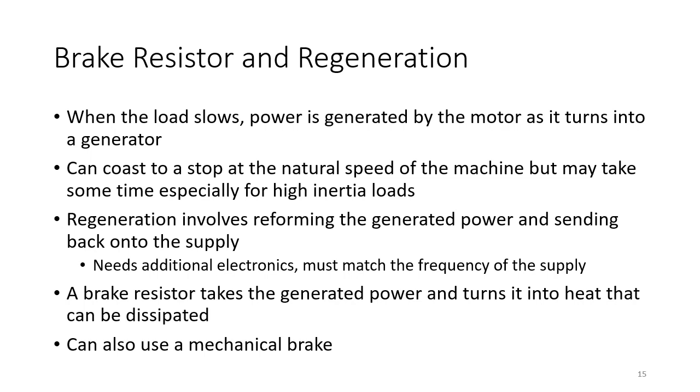What we can do is regenerate the electricity. This involves reforming the generated power and sending it back onto the supply. You probably experience this if you've ever been in a modern car, particularly an electric car. When you take your foot off the accelerator, we use regeneration to take the inertia of the vehicle, convert it through the alternator of the vehicle or the electric motor of the electric car, and turn that into energy that can be fed back into the battery to recharge the battery.